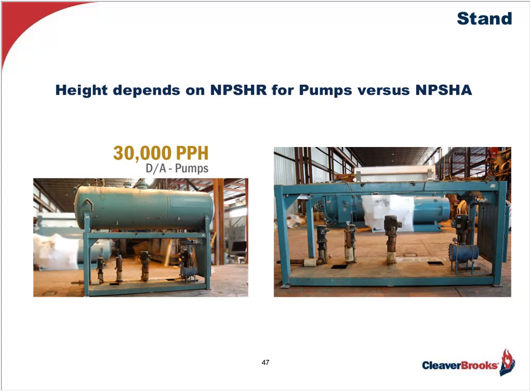We also know what our pumping requirements are, with a flow rate of, say, 16 gallons per minute and a TDH of 328 feet. Taking this information, we go to the pump curve example I just showed you and find we have an NPSHR requirement of, say, 5 feet, meaning the stand must be constructed to give me a minimum of 5 feet above my pump's inlet center line, measuring from the normal water line in the tank down to the center line of the pump's inlet, and this is to prevent cavitation.